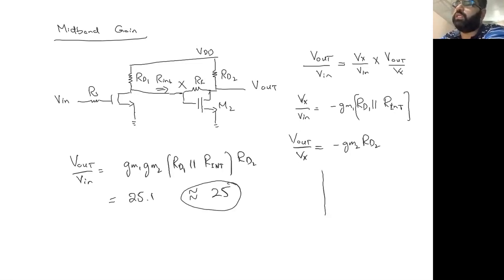So now we know this amplifier's low-frequency corner was determined by omega L1. This gain value is 25. And now we need to find the corner where it starts dipping down again. Okay, so we have to find the dominant one again in the high frequency. In the low frequency, the dominant frequency is the highest one, and in the high frequency, the dominant frequency is the lowest one. So for this, we again have to do something similar to what we did in the two previous lectures: bring in the parasitic or transistor capacitances.